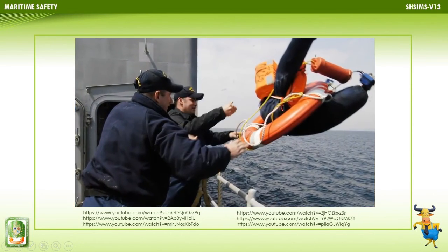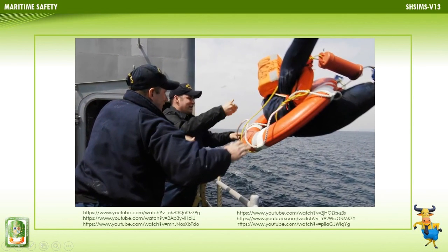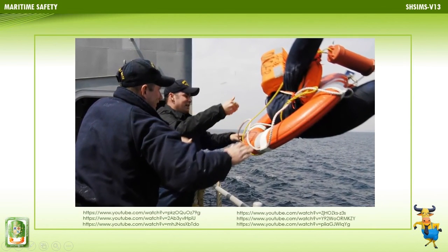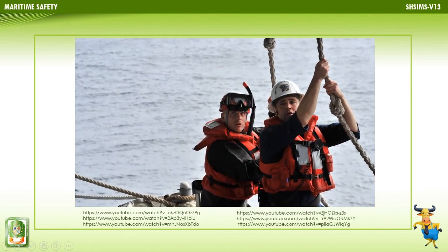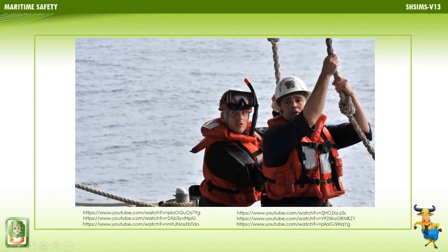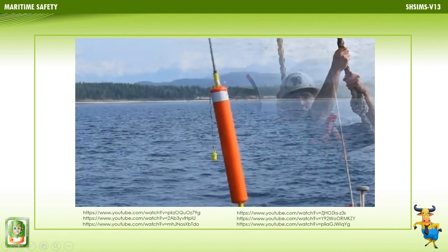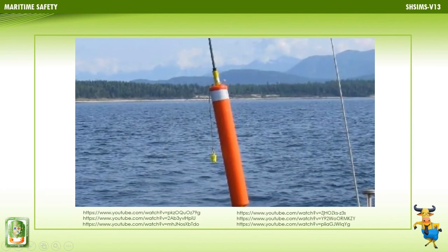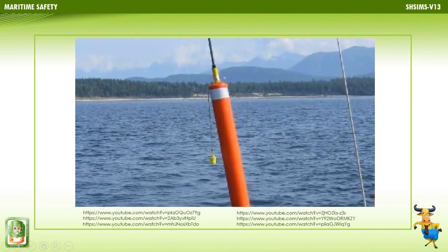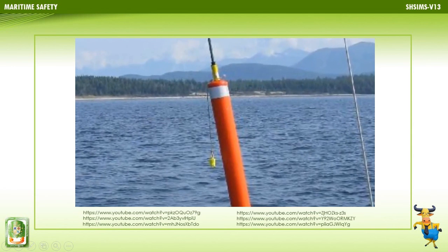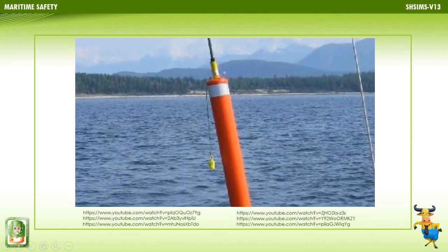The immediate response taken by the crew member witnessing a man overboard or realizing that a crew member is missing: shout "Man overboard." This will alert all crew to the emergency situation. Deploy a Dan buoy, life ring or similar to provide a floating datum. It does not matter if the person is visible at this time or not.